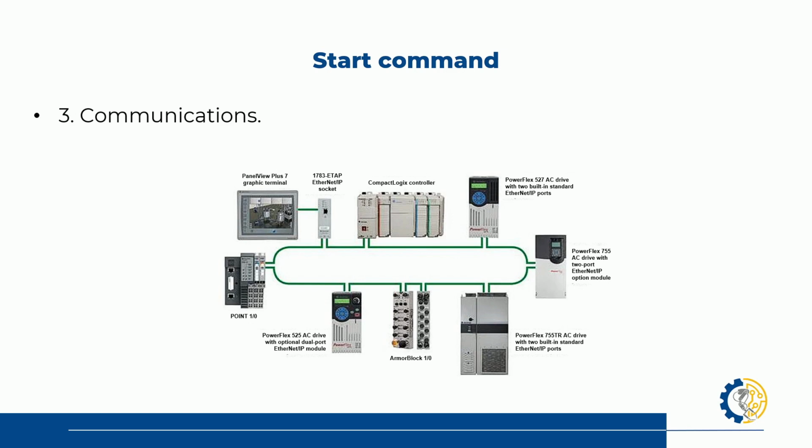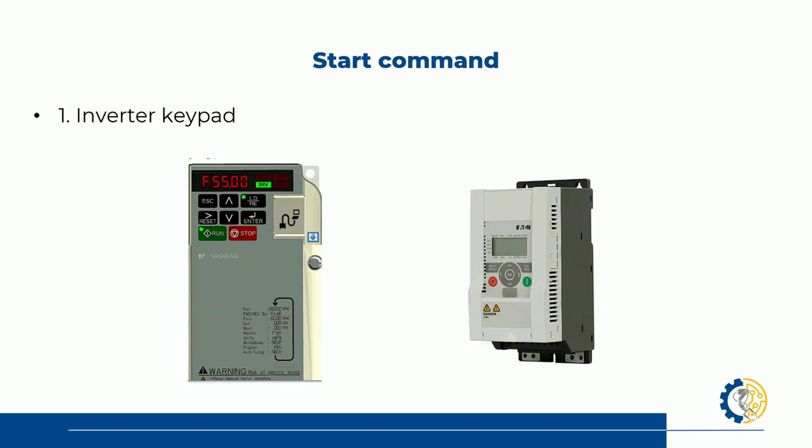Always in a drive we need to have the start button and the stop button in a motor. So that's why I need to tell my drive about that parameter. I have to look for it in my manual, and I need to tell it through the parameters. I need to know what option is going to be the right one according to my application.